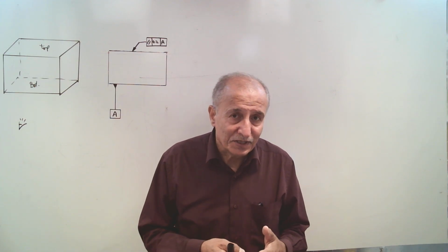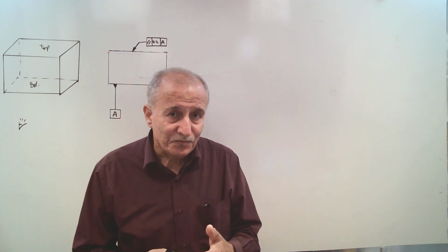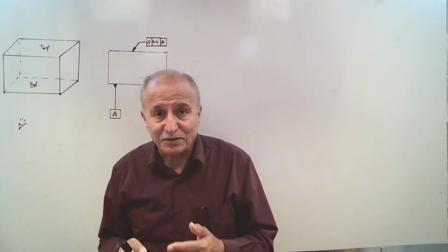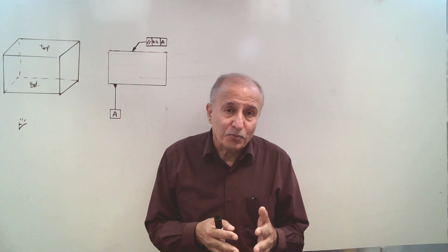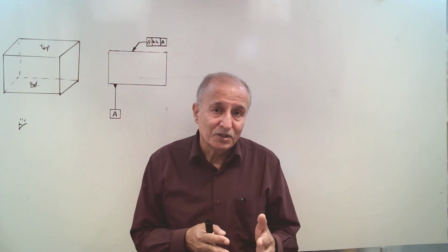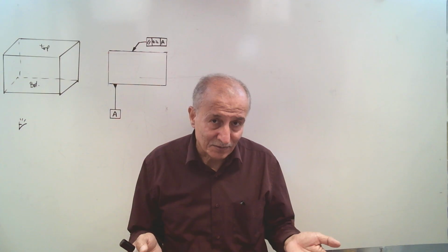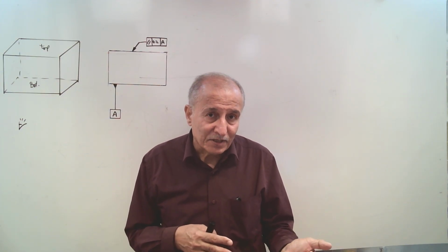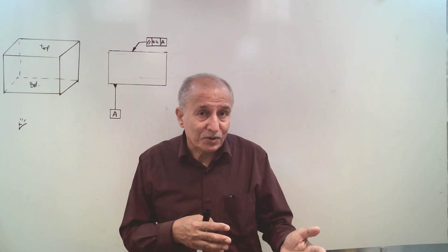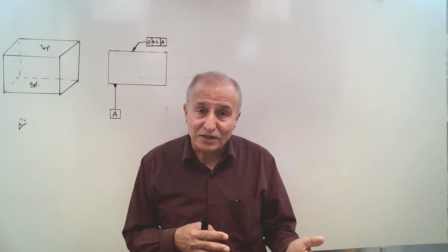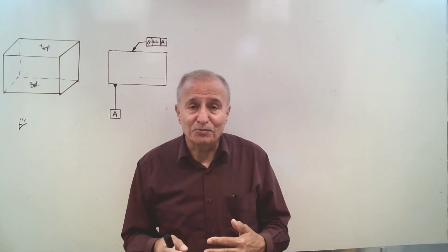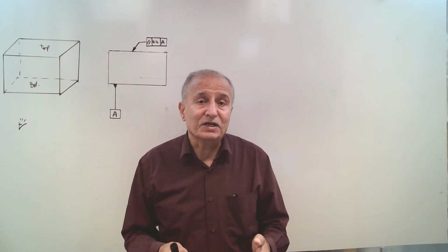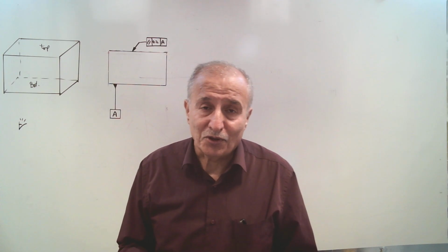What does refinement mean? It means that if you specify the position of this surface with respect to a datum, position control indirectly controls parallelism as well, or perpendicularity or angularity. But if the focus is not only the position and also parallelism, angularity or perpendicularity are important, you must specify a tolerance for that orientation as well.